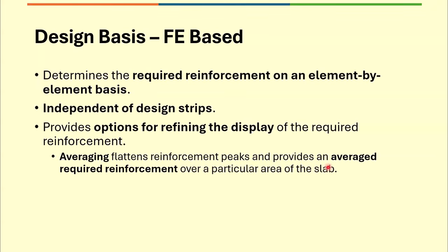So there are two design bases. One is finite element based, and the other one is strip based. The finite element based is always available when you perform the design, irrespective of whether design strips are drawn or not. So you can always refer to this output, but we recommend the design strip method over the finite element based.